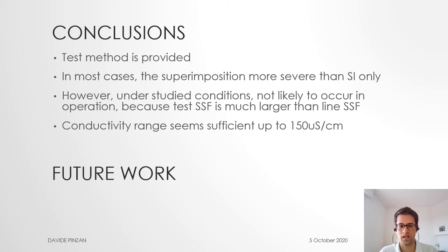The conductivity range seems sufficient to be studied up to 150 microsiemens per centimeter because after this value, the results saturate. The flashover voltage tends to saturate.